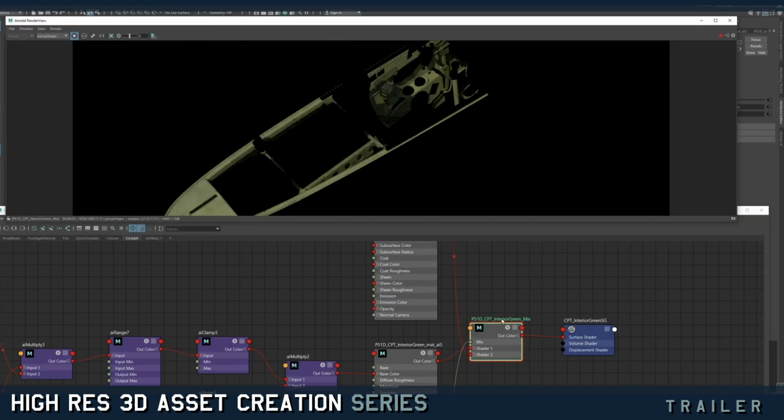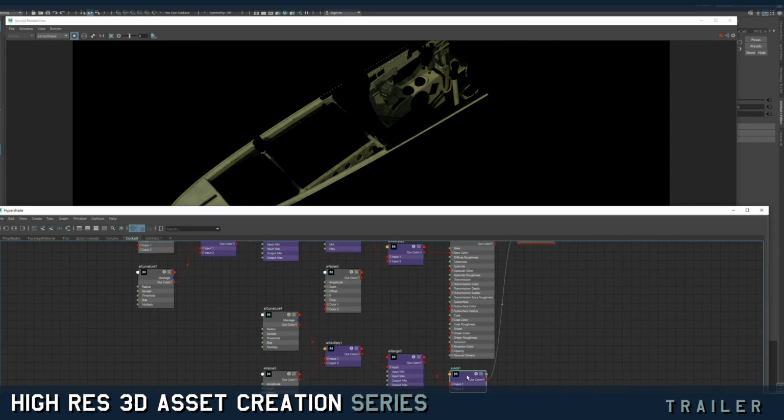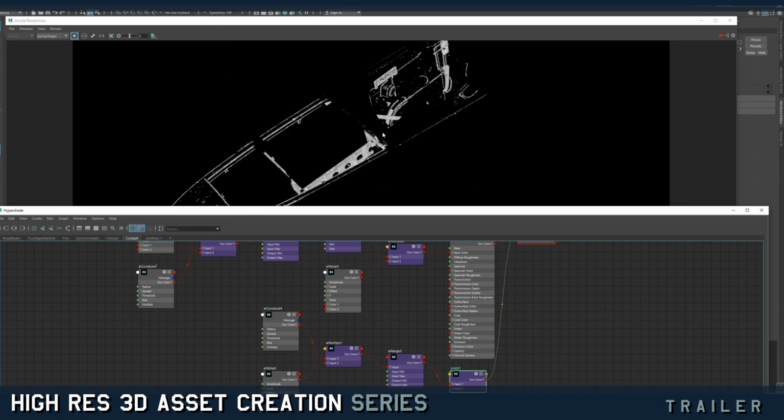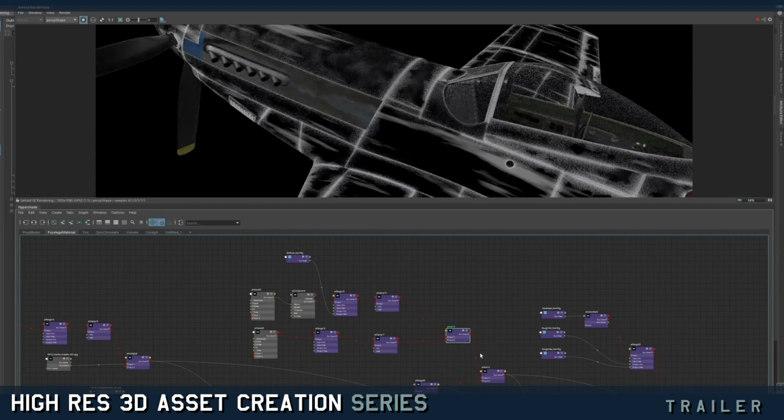So you can see that this is a mix shader. So this is basically mixing two materials based on another input. So what is this input? This is basically just a black and white texture. So there can be values above 1 basically, and even below 0. So as a precaution, I don't always have to, but you should really, when you're just dealing with something like an alpha mask input, clamp between 0 and 1 to not have any negative or positive larger than 1 values right here.